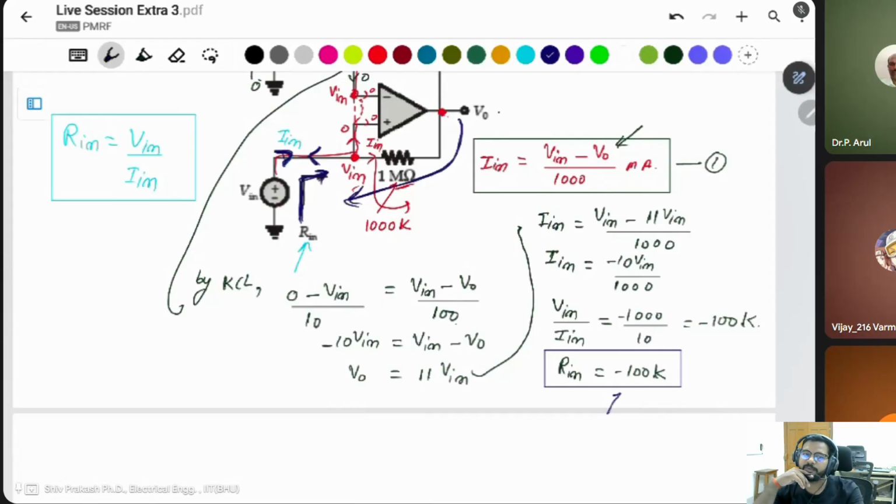In physical quantity, resistance is never negative. It should be positive. Just because of the amplifier, and some circuits where a dependent source is connected, it is possible that the equivalent Thevenin resistance may be negative.